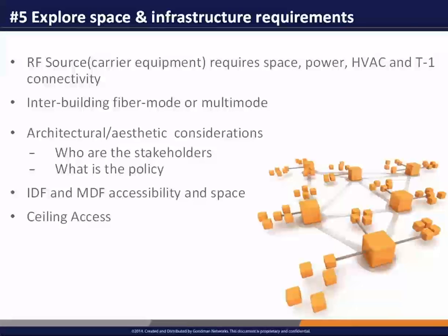Similarly, with the base station requirement, you're going to have some remote IDF and MDF requirements. The remote hubs are going to need to reside typically in an IDF or closet. And at the same time, you're going to have thousands of feet of coax and or fiber that's going to be typically run in ceilings. So if you have plans, architectural drawings that show existing pathways, or you understand the best means to pull cable above ceilings, that's going to be invaluable information to give to the RF designer. And if you don't have that, then that is something that will need to be understood fairly early in the design process.